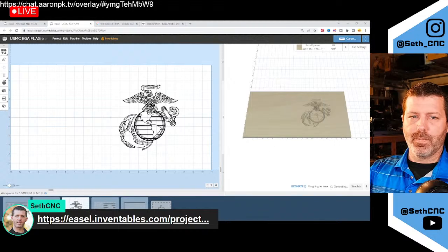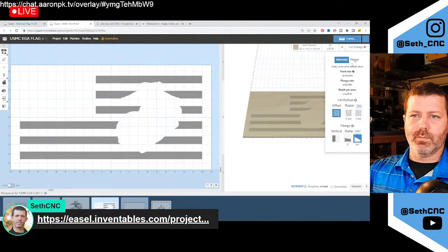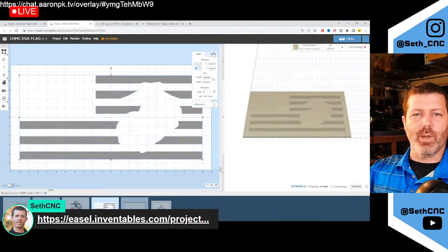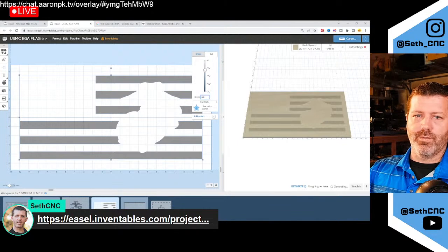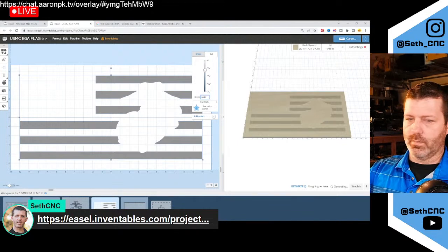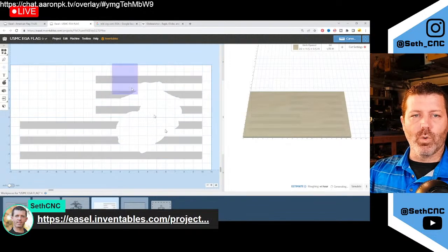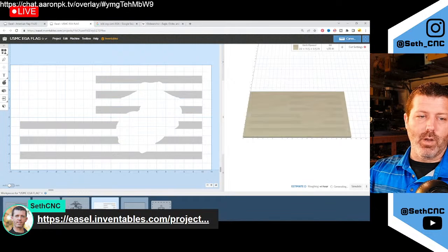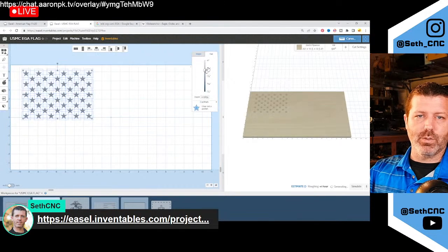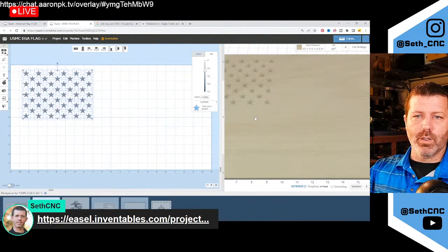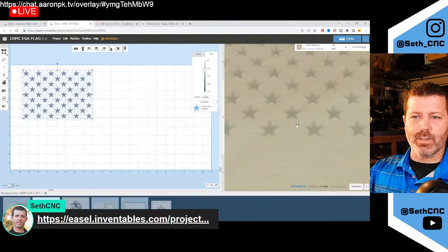All right. And then what are these guys set to? We can ramp these or we can not. The way that I carve this. Oh yeah, I didn't really set the depth the way I like them. So the depth for these stripes, usually I do about 1 millimeter or 0.04 inches for the stripe depth. Now all the V-bit stuff we want to set to allow it to generate the depth by itself, right?